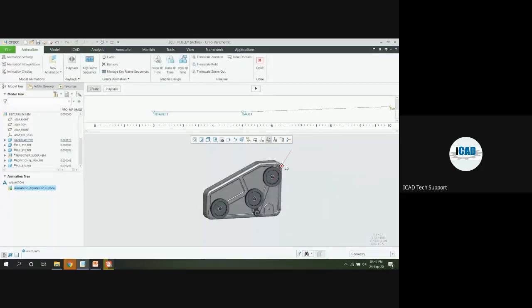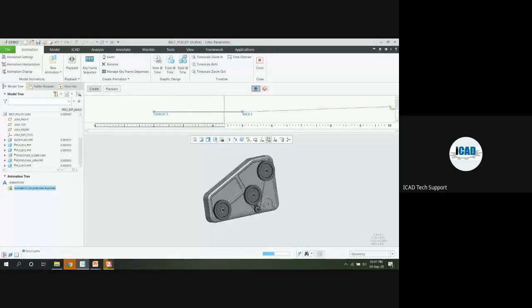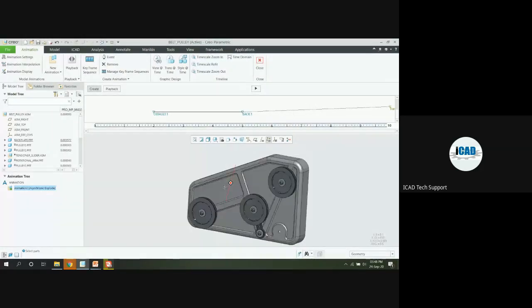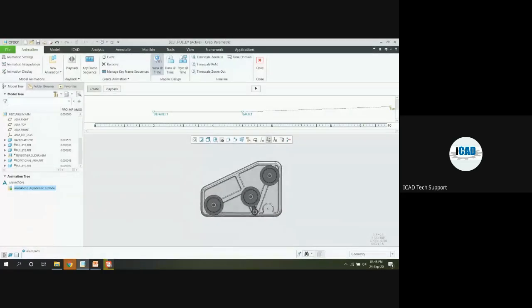Click on close. Now I want to play whatever animations we have created. Just click on the play button. The video automatically gets played. And you can see the transparency option will get applied automatically, and our parts orientation we can set from here. The time domains are available for at what time we want to see it. So this way you can add multiple views again, from back to start to default. You can change the colors as well.